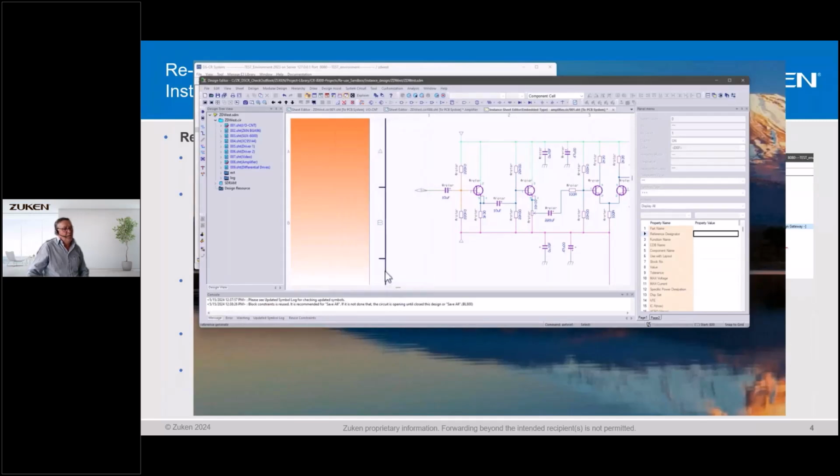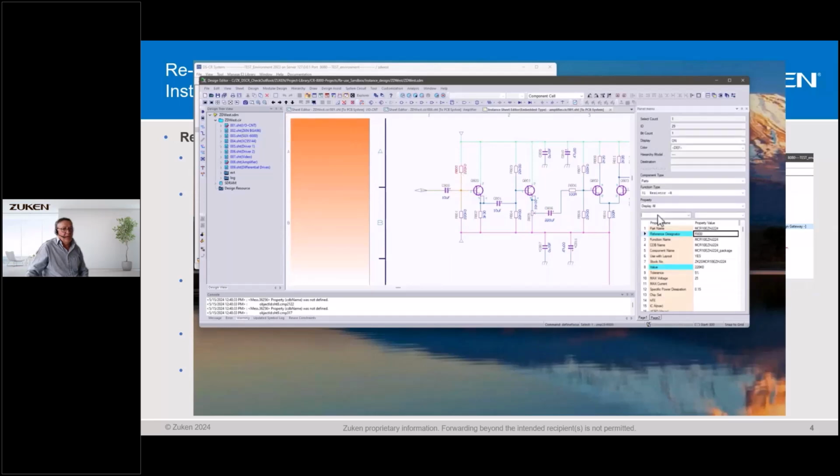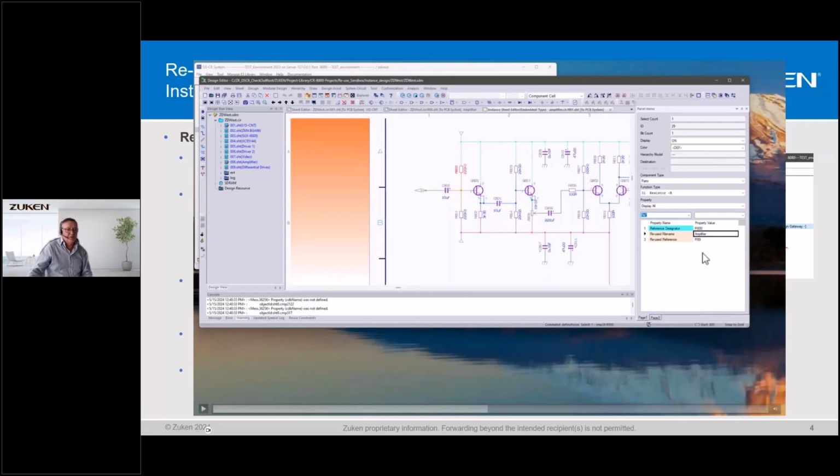And we simply get new reference designators allocated, all beginning with 800 and higher. Now I want to show you also the key functionality which is necessary to reuse the component position and the routing of my layout module. There are two properties, and that's why I put this RE asterisk in the filter line.